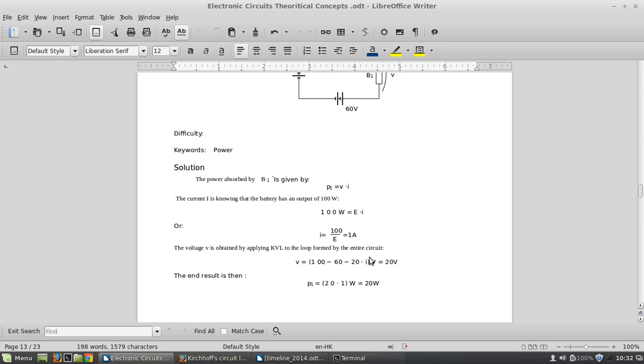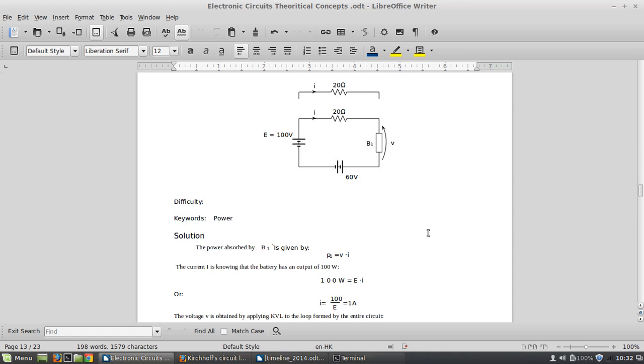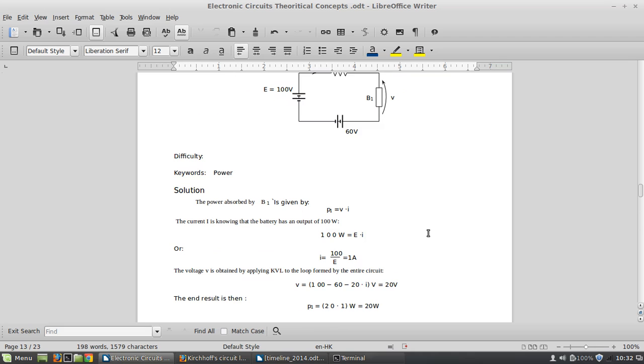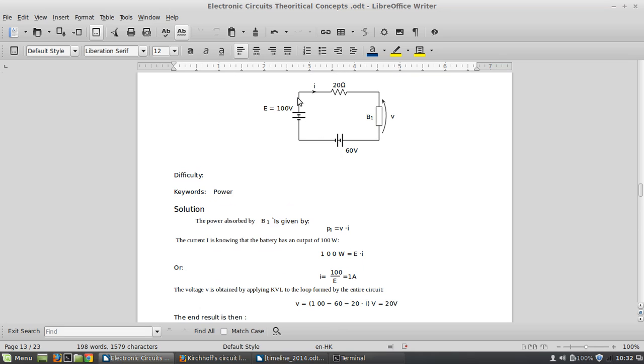The current will also be the same as I. Now, knowing the current, the voltage is unknown, so to find the voltage we use the mesh in this whole circuit. We take the mesh as a whole, and this is a known voltage, this is a known voltage. Knowing the information of the resistor and the current, V equals IR using Ohm's law, right? We use this, and we also find this particular voltage here. And that's it, that's how we use it.